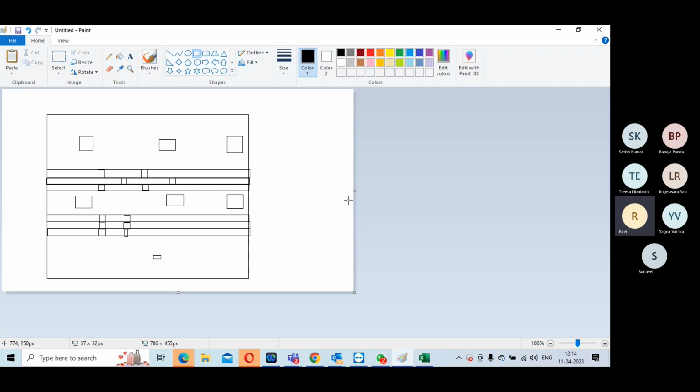That's where the fly line connectivity between the macros comes in, I told you. You can still enable the fly line after doing module based, hierarchy based placement, and if you still see that macros at the bottom are connecting to something at the top, that is what will be shown by the fly line. You can understand why that is happening. You need to ask the designer why this is connected, can we split, or is it supposed to sit there as per the module. But if he says that no, they need to be closer only.